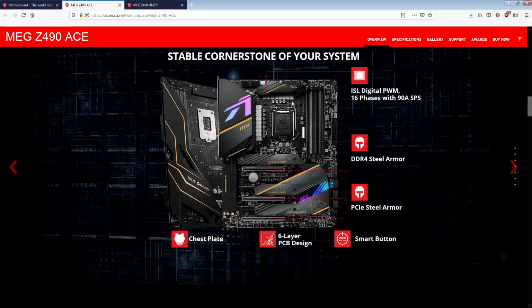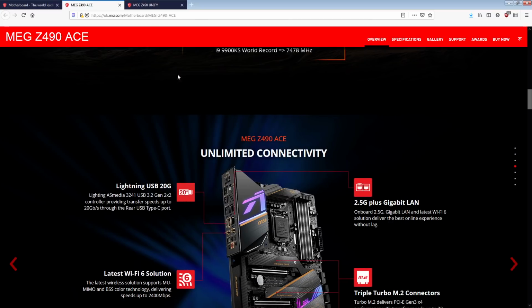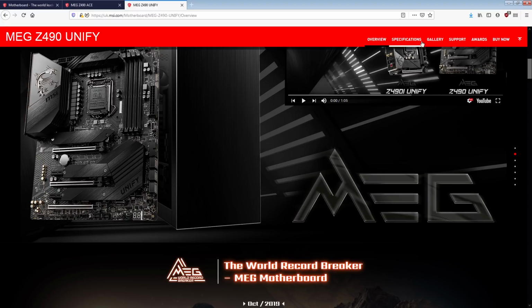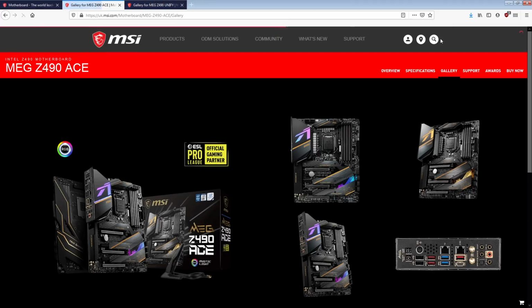I'm definitely building a Z490 probinator, so I can take oscilloscope measurements of the voltage regulation on all these boards. And unlike with X570, it won't be tedious AF and likely to break boards. Anyway, so the power delivery, you get the same power handling capacity as the Godlike, you just get slightly worse voltage regulation.